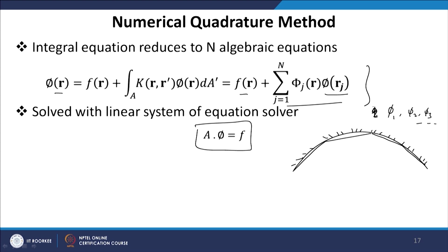Now, in quadrature, we are not selecting flat surfaces, we are just taking the quadrature points and evaluating our function at those points. We assume that if we evaluate the quadrature in this way, we can approximate the heat flux over the entire enclosure. So, this method is much more accurate than approximating the enclosure with flat surfaces. I will show you one graph explaining the accuracy of this method.